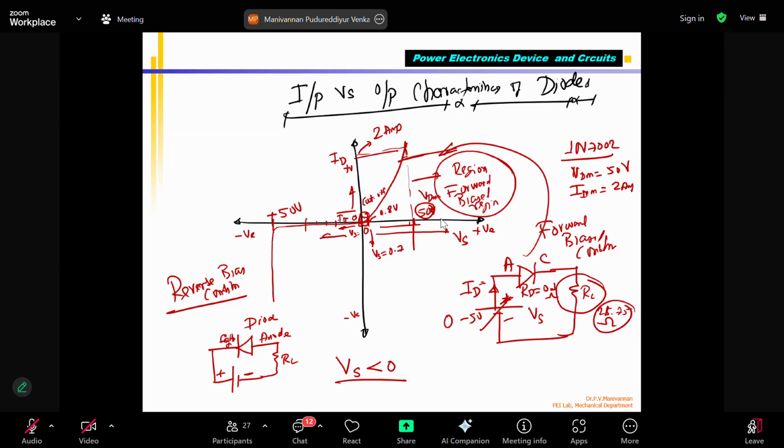Once the voltage exceeds 50 in the reverse condition, you will see the current in the negative direction, a negative current. That means if current flows from the battery, it is a negative current. Up to then, as you increase the voltage, 10 volts, 20 volts, 30, 40, you can see the current is almost 0. On the Y-axis, the negative side is close to 0, maybe a few milliamps.